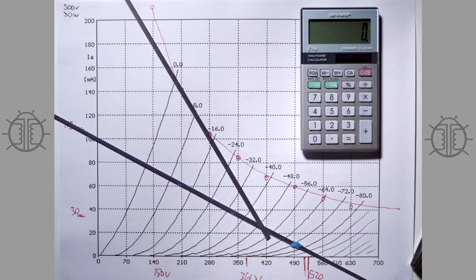So calculating the power of Class AB output stages is more difficult because the sine wave from each tube is no longer sinusoidal. And so you can't just do the average voltage by the average current again times 2 for 2 output tubes. You end up with a little bit more than that in the area that sweeps out.